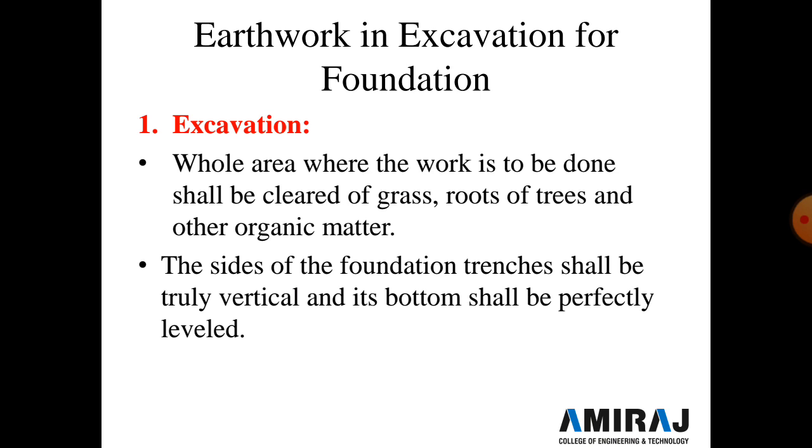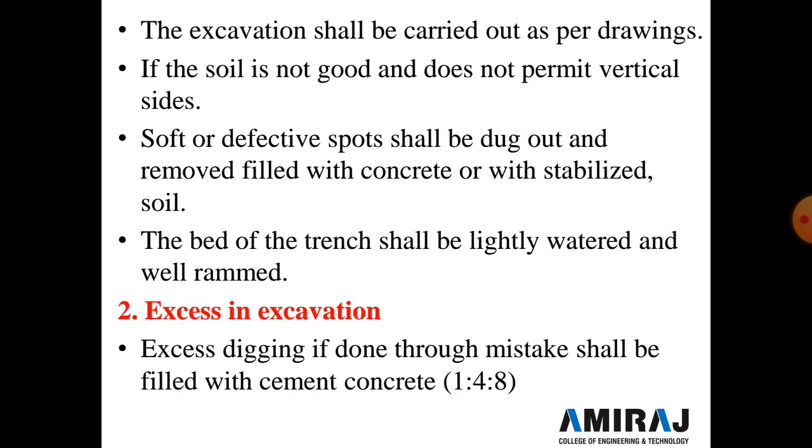So first is excavation. Before the earthwork excavation is started, the whole area where the work is to be done shall be cleared of grass, roots, trees and other organic matter, and the sides of the foundation trench shall be truly vertical, and its bottom shall be perfectly leveled. The excavation shall be carried out exactly in accordance with the dimensions shown in the drawing, or such other dimensions as the engineer in charge may decide.